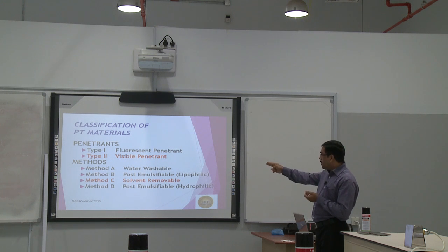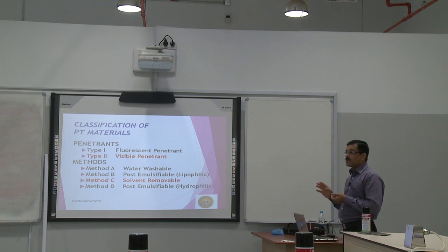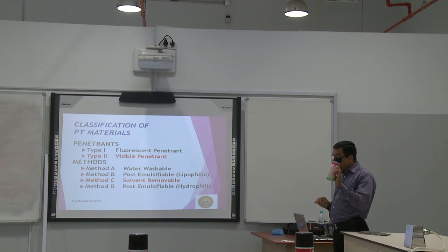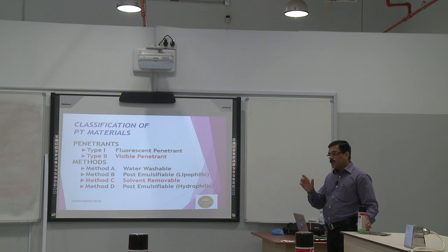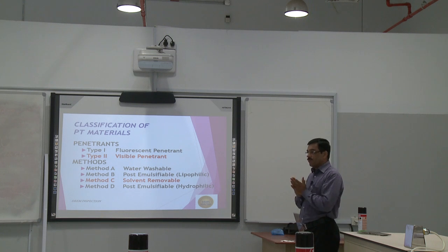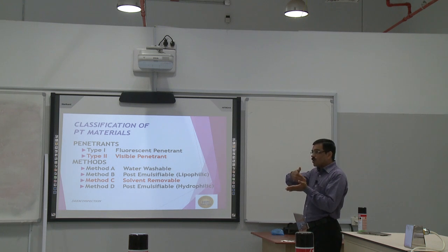Another, B and D, are very rarely used, but they are good sensitivity methods: the emulsification method. Usually we apply solvent penetrant, and after the dwell time we apply a thin coat of emulsifier, like a chemical emulsifier.